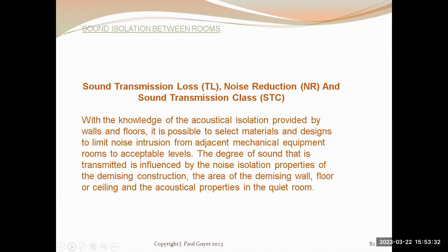sets the chipboard into a vibrational mode, acoustic energy. And that the chipboard then sets the steel studs into a vibrational mode on a microscopic scale. And then some of the sound is transmitted through the air gap between the studs.